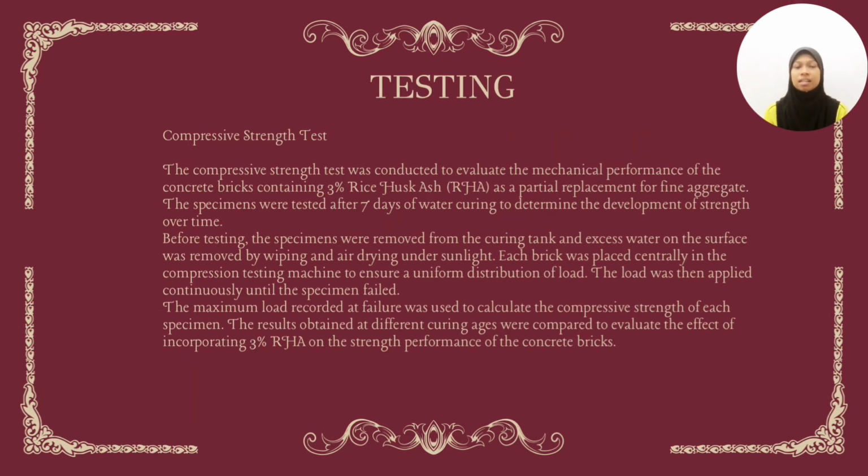Compressive strength test. The compressive strength test was conducted to evaluate the mechanical performance of the concrete brick containing 3% RHA as a partial replacement of fine aggregate. The specimens were tested after 7 days of water curing to determine the development of strength over time. Before testing, the specimens were removed from the curing and excess water on the surface was removed by wiping and